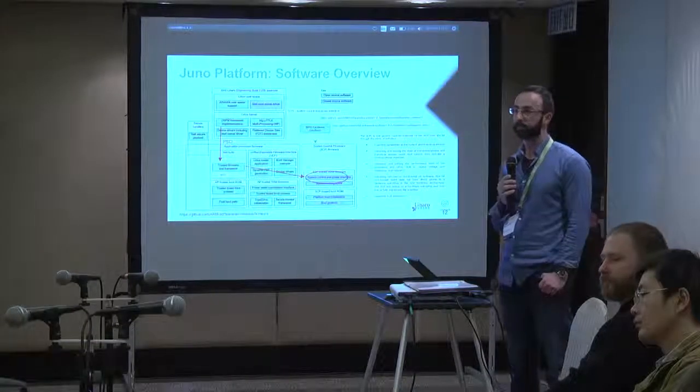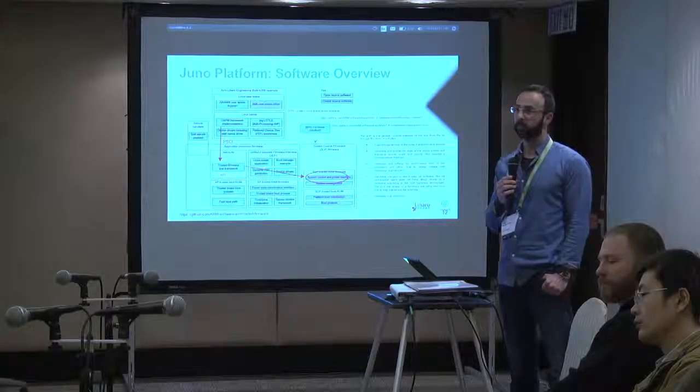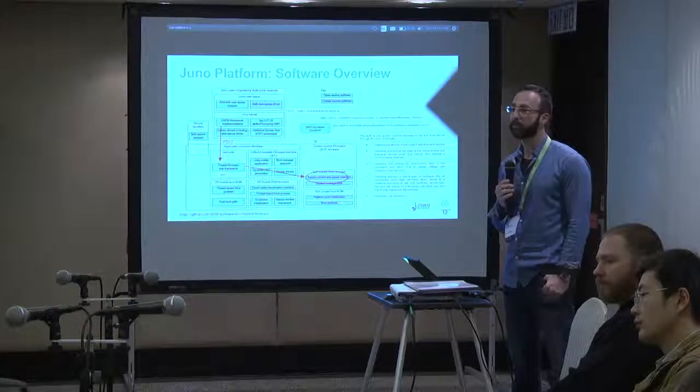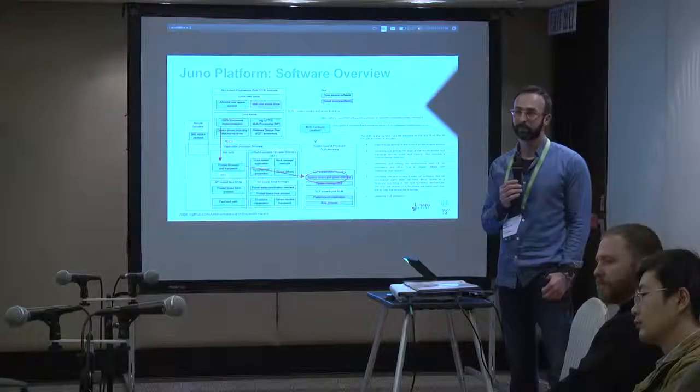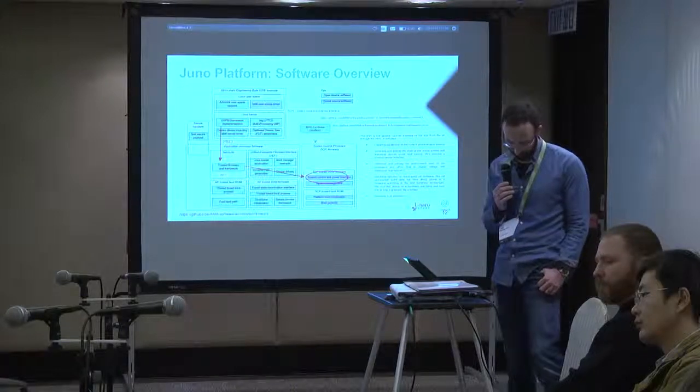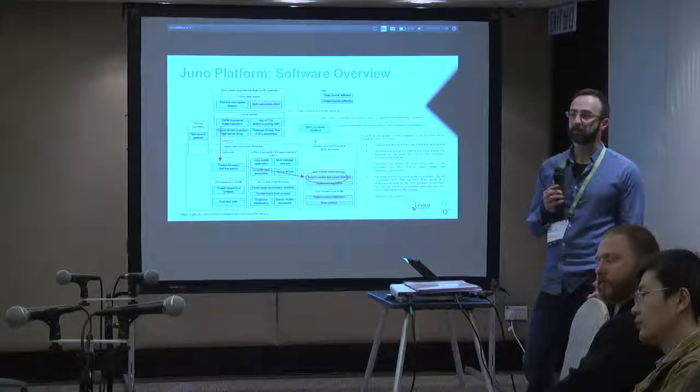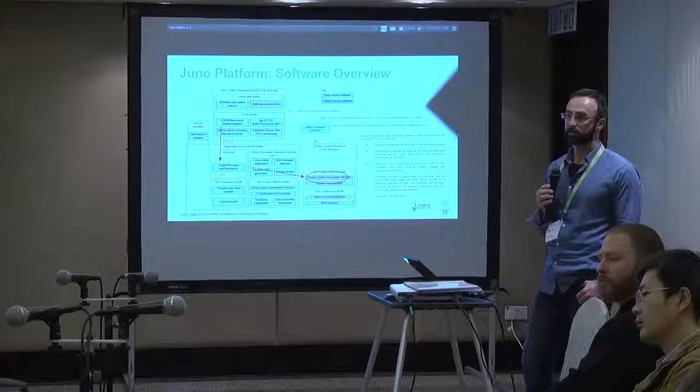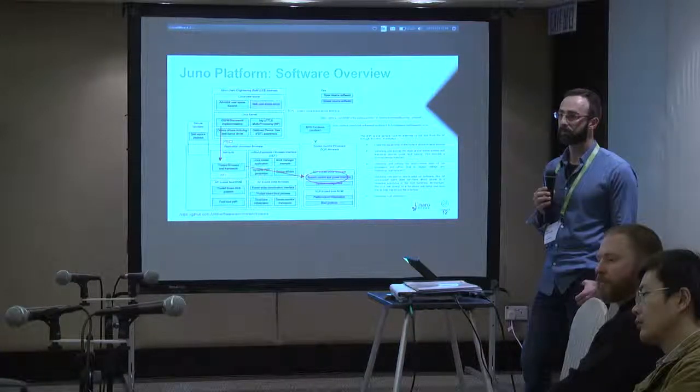ACPI already has a sort of standard for some of the DVFS operations, which is CPPC. So in the interest of supporting that, one of the things we have been looking at means actually re-engineering the way we're using the hardware MHU channels.